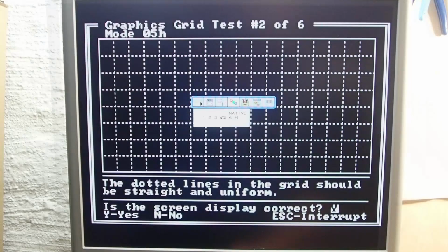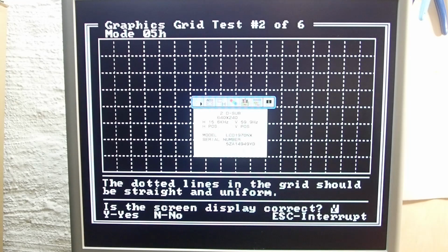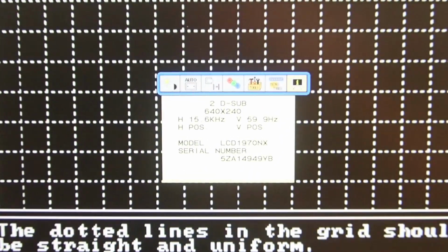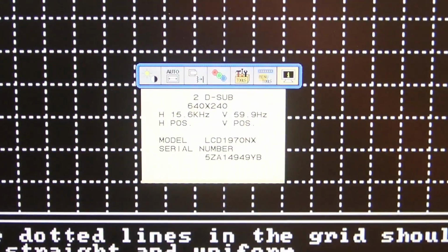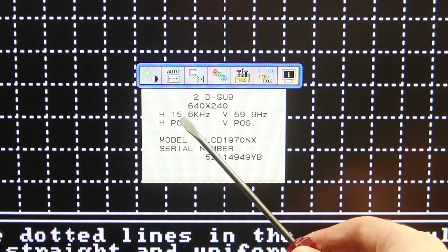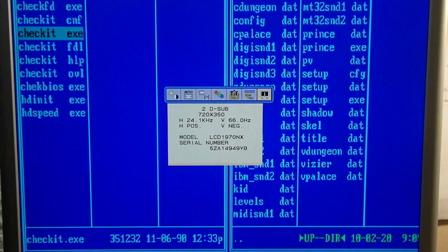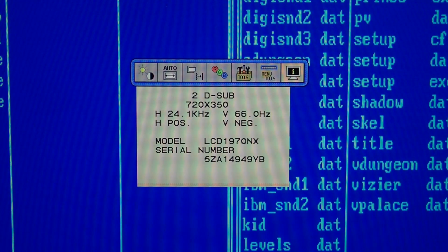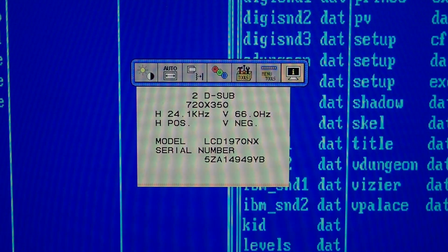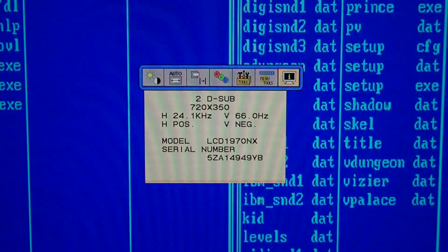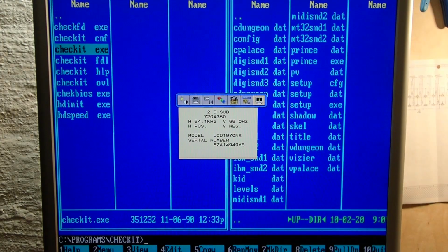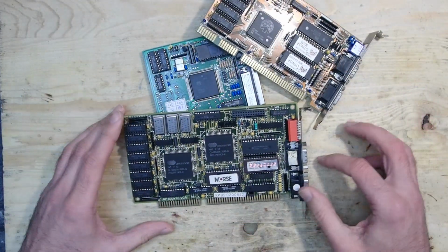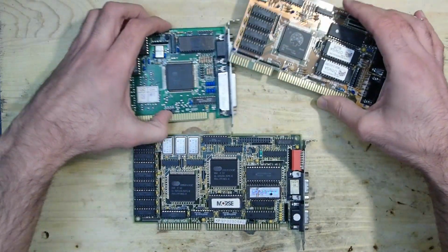I think I still owe you an explanation why high-resolution EGA didn't work with GBS-8200. Take a look at the frequencies which the monitor reports. With CGA and low-resolution EGA modes, it says 15 kHz. But with high resolution, it tells 24 kHz instead of the standard 21 kHz. I measured the frequencies with my oscilloscope, and I can confirm that the card delivers 24 kHz instead of 21 kHz. Unfortunately, both of my EGA cards deliver frequencies somewhere between 22 and 25 kHz.